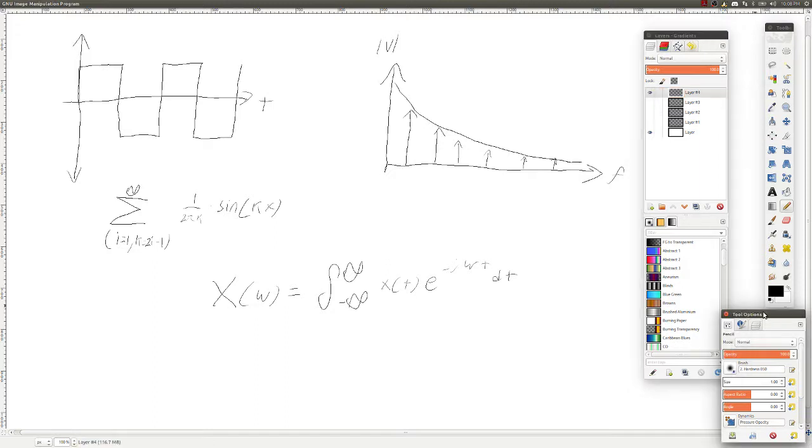But this does give us a tool. If you remember, we want to transform this I equals C dV/dt, a time domain dependent function relating voltage to current, into something that's frequency dependent so we can use impedance. So you want to turn this into Z of omega. Now we have a tool to convert between time domain and frequency domain. So we can actually convert this function here into something like impedance.